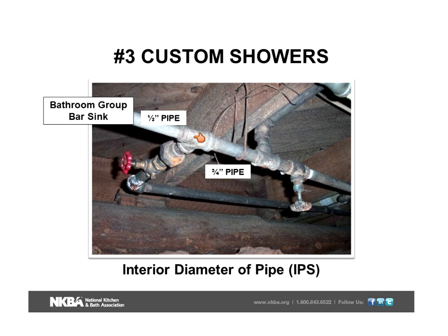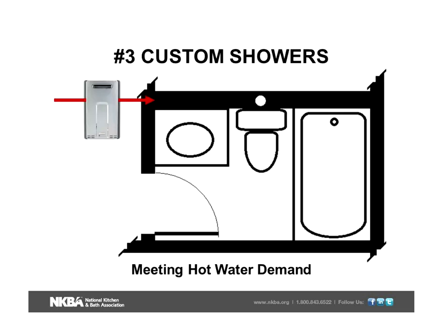So this is exactly what I'm talking about, and these are the things you need to look for on your projects if you're making that upgrade. So keep that in mind: 1 to 2 fixtures, 1/2 inch; 3 or more, we need 3/4 inch.